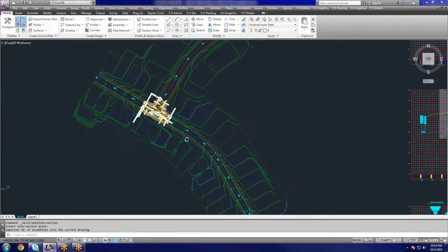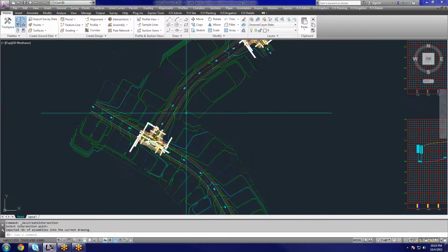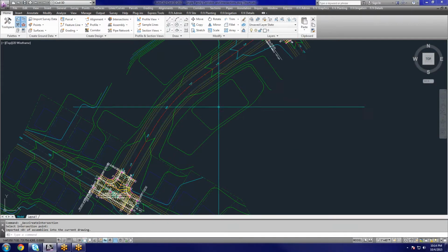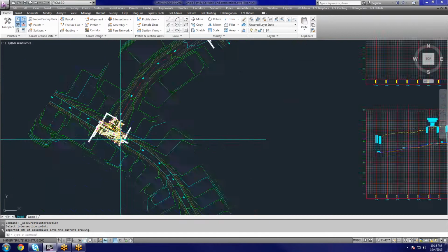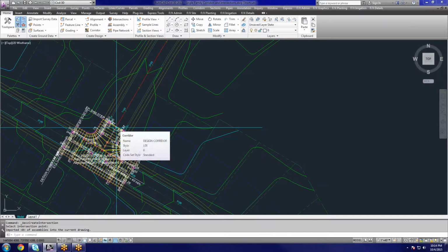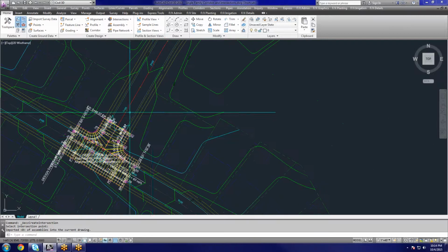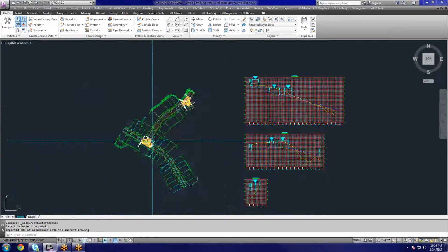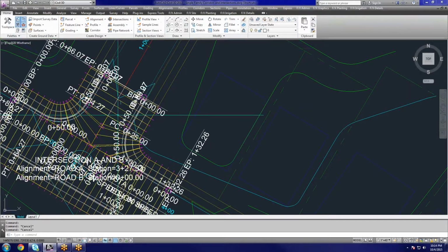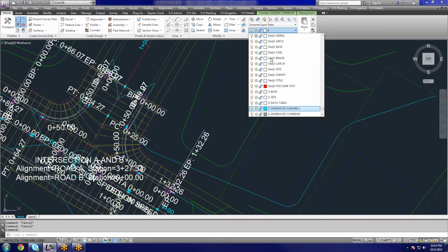So this is when we're going to fill in the regions in between with the full sections of our main portions of our road. So from here to here, and whatnot. We're basically just going to pick up from the station where these intersections left off for each respective road, if that makes any sense. So let's go ahead and throw our corridor on a corridor layer, Z generated corridor.